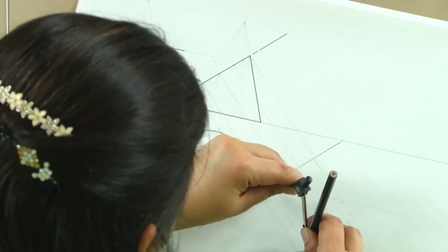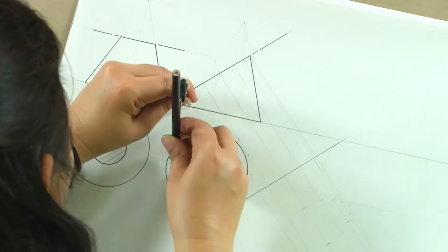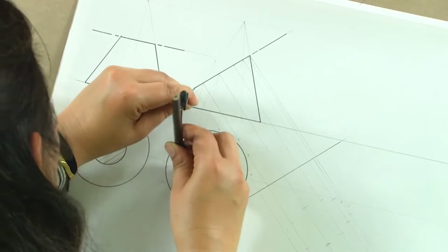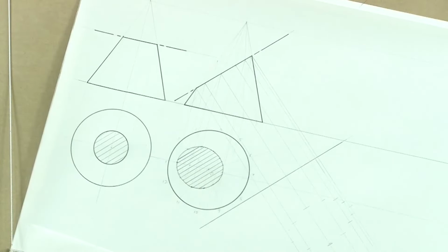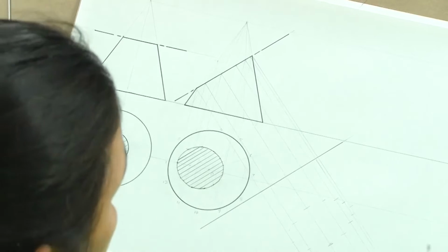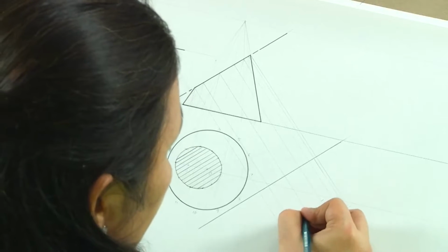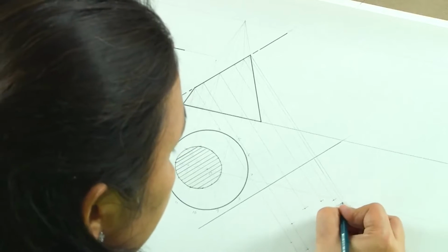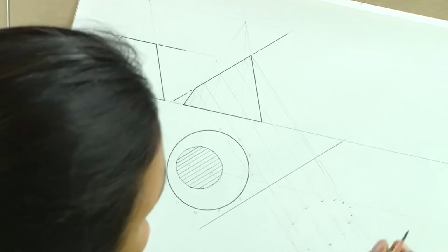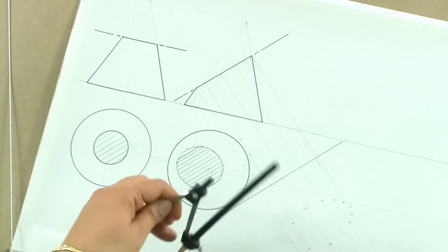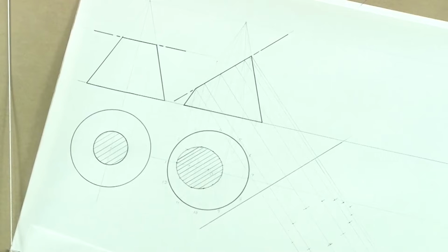So, orthographic projection might appear to be a tedious thing to do, but it is quite scientific, and once you have got a grasp of it, it becomes fairly simple to arrive at the solution. So, these are the points that we have, and if you can make out a shape, you can clearly see that we have arrived at a perfect ellipse here. So, let us again try to fit the French curves here.